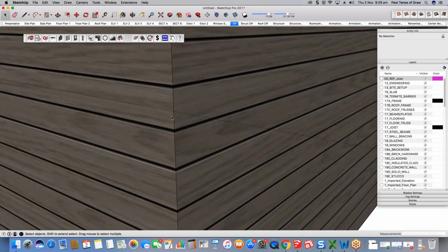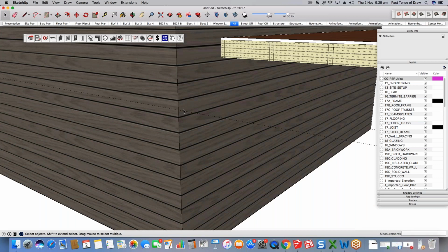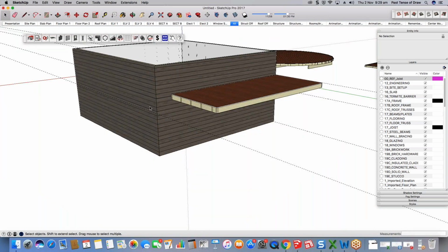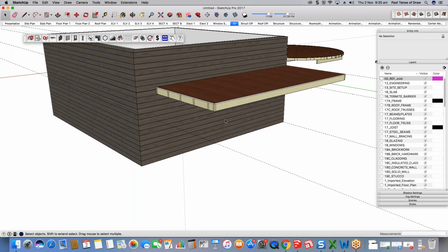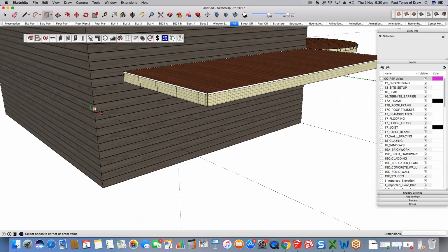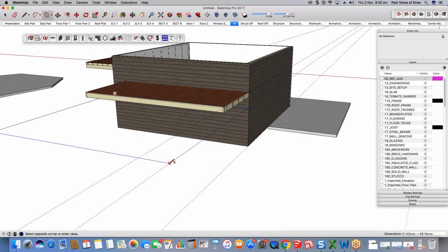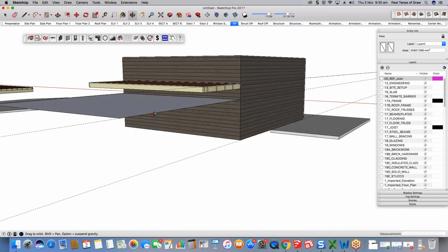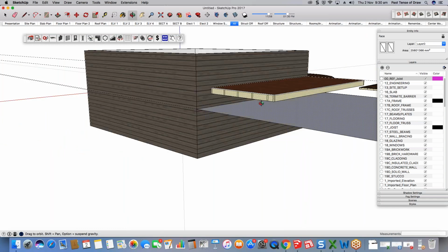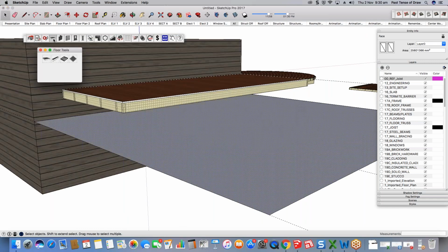The biggest problems happen when you don't look at where you've pointed or what you've actually selected, especially if you have the ability to choose different planes or different heights. So if you are going to be modeling in that way, you really need to be very careful that what you're clicking is accurate. Alternatively, if you're a little bit worried, that's when it can be very useful to use the SketchUp face tool, etc., because no matter what you're doing here, I'm stuck on the blue, and therefore I'm always going to be drawing on that horizontal level. Again, I can go back into my flooring tool and select my joist.